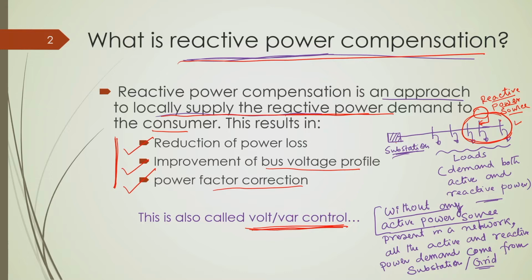Okay. And of course, reactive power source placement needs some additional investment from a utility, and it will also cause certain problems, because you know capacitor switching will cause some serious transients. So, keeping all this in mind, placement of capacitors is an important approach to reduce power loss or to improve the voltage profile, and that is why we do it.